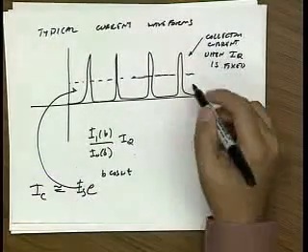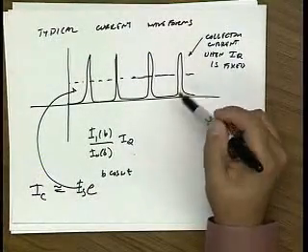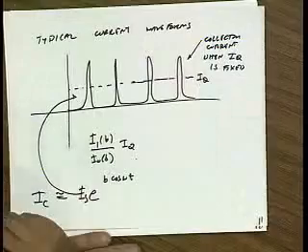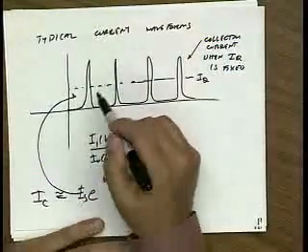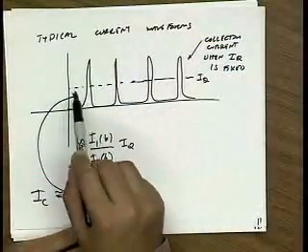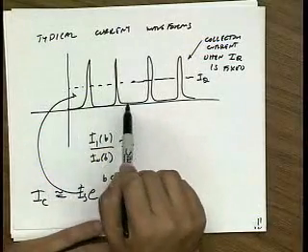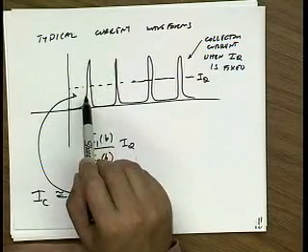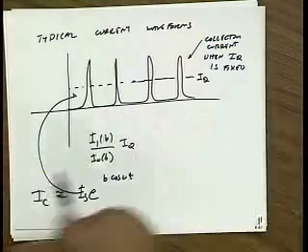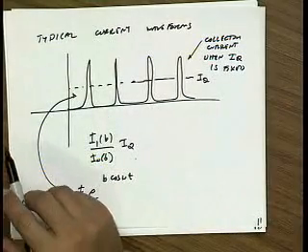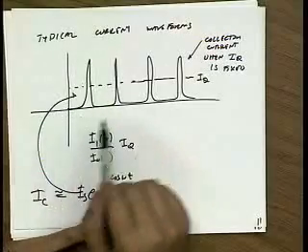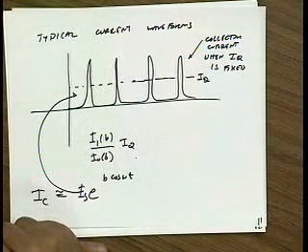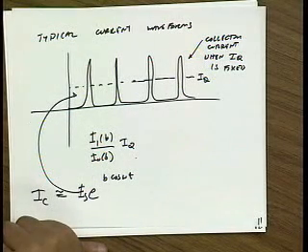And the idea is that if this bias circuit can't respond fast enough to keep the bias constant, then, it's hand wavy here, so bear with me, what's happening is that this peak has to be just right in order to make an energy balance happen, right? And if the circuit prevents the peak from getting too large, then you might not be able to deliver enough energy into the tank. So if that capacitor is too large and it doesn't let this peak go high enough, it will prevent you from going into steady state. You can never get enough energy. So even if the loop gain becomes 1 for a small time, it won't be able to hold that state.